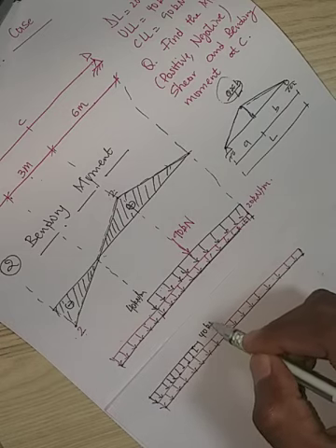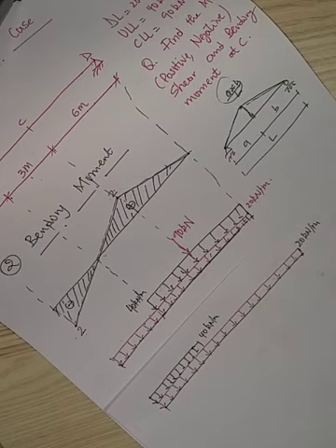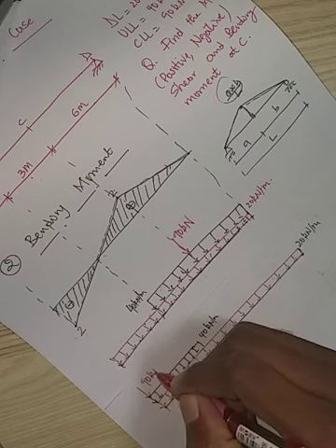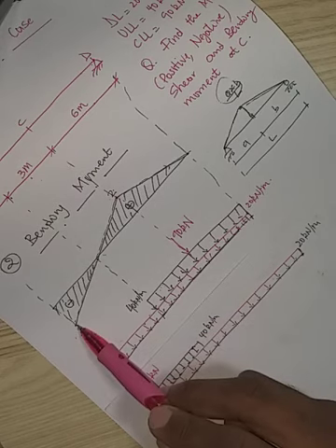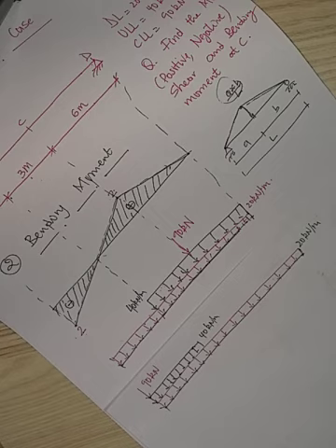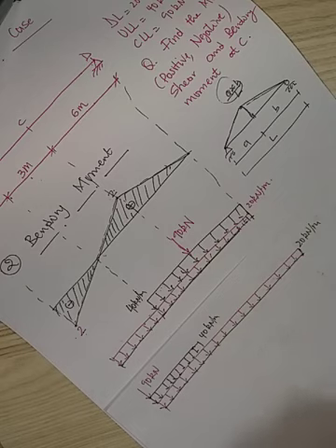Here we have 20 kilonewton per meter, and then we add our concentrated load of 90 kilonewton applied at the position of the maximum negative ordinate in the influence line for the bending moment. After having this configuration, we are sure that we're gonna find the maximum negative bending moment at the cross section C.